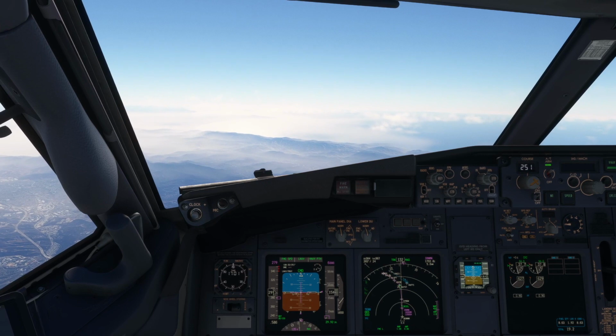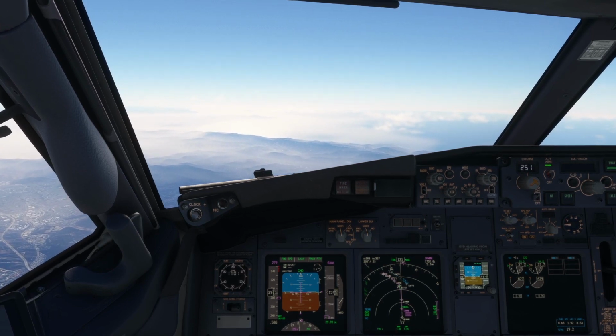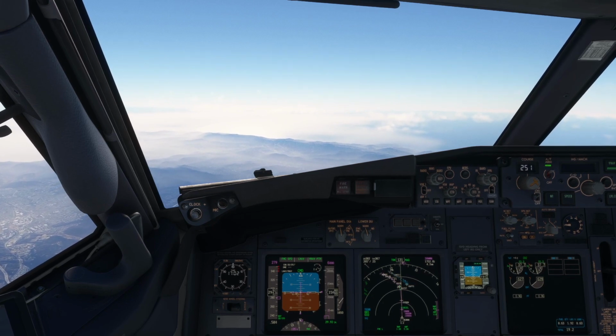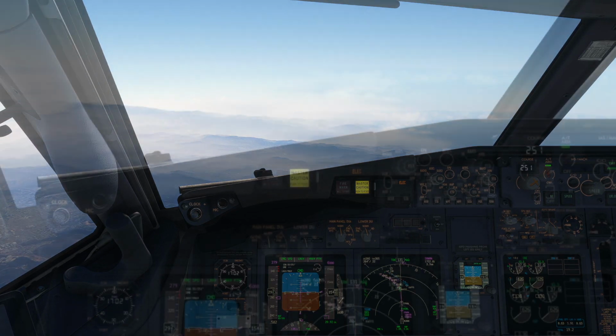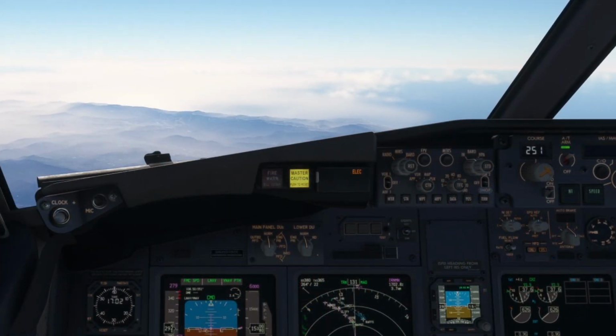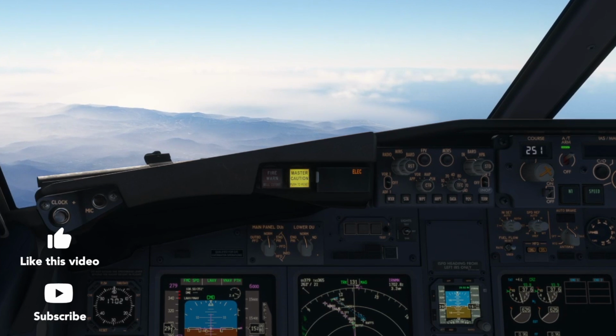Let's join the flight as we descend on an arrival into Los Angeles International Airport, California. As soon as the master caution light and electrical annunciation illuminate, the pilot flying states, "My aircraft." Once verbalized, the master caution button can be pressed to extinguish the light and avoid distraction.